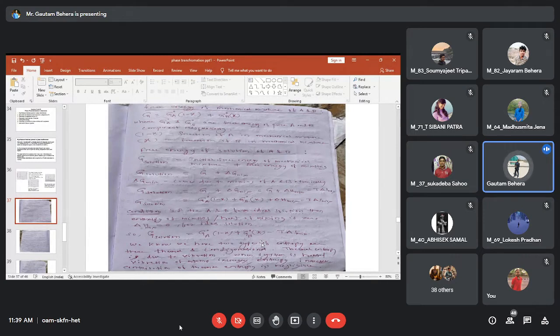And we know we have two types of entropy. You people remember already from the earlier lectures, we can have two types of entropy. One entropy will come due to vibrations, lattice vibration of atoms, molecules, right? And that is due to change in temperature. If you increase the temperature, the vibration will be more and more and more. So that is called thermal entropy, entropy due to vibration, or some people call it vibrational entropy, right? And another kind of entropy will come into picture if you are having an alloy or a mixture, right?